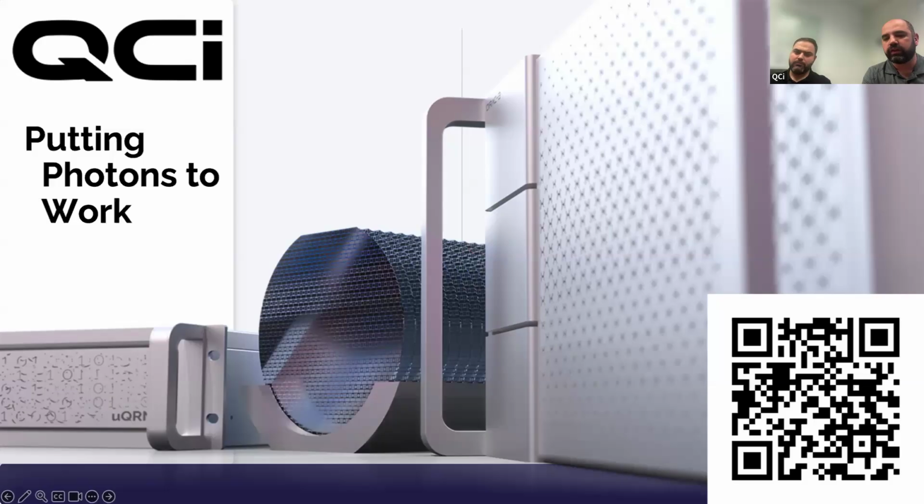And there are several things that contribute to that low yield. One is the lack of in situ monitoring of the poling process. That's something that we're actively working on. The other one is just the height variation of the waveguide, which can significantly affect phase matching. That's another project that we have to tackle. So at the moment, it's not yet a wafer scale technology, but that's something that we're working on quite actively in the near future to overcome.